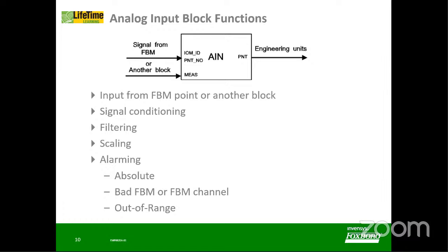Now, in the Foxboro DCS system, whatever blocks we have, we call them function blocks. All these function blocks have more than 100 parameters which you can set or change. As many parameters as you need to understand, you need to go through the document provided by the DCS system, where each and every parameter has some meaning, and based on that you can use those features as per the customer requirement.